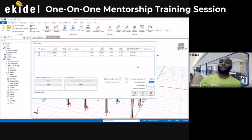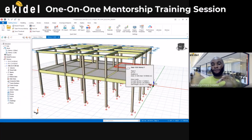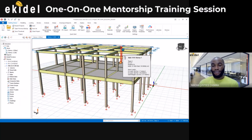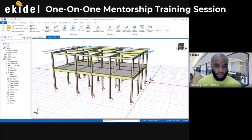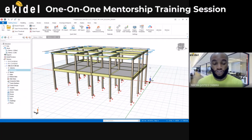Okay. That's fine. So once you're putting your heights and everything, and then you put your DPC level and then foundation depth, you can leave it as default because it might change later. Then come here and click on OK. And then say yes. So you can see that the height just increases. If you now check this, you can see the height has increased: 0.9, 4.2, and then 7 point this. I see that? Exactly. Yes. So it automatically sent it up, no? It did the calculations. Yeah.